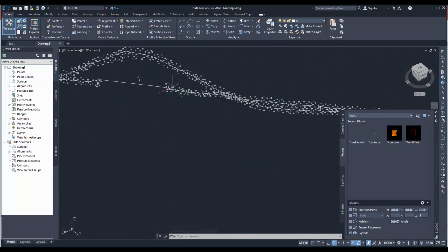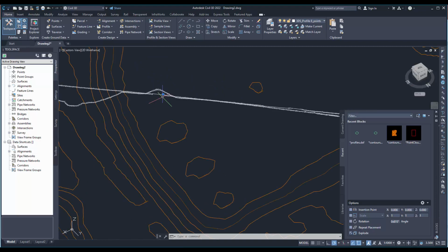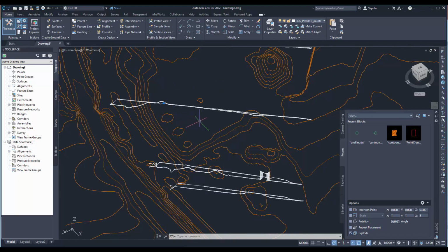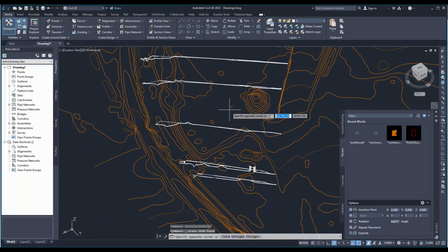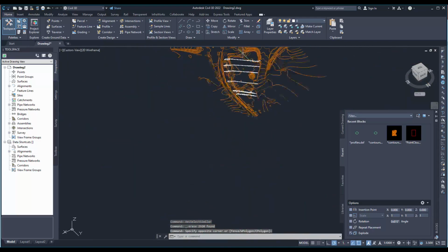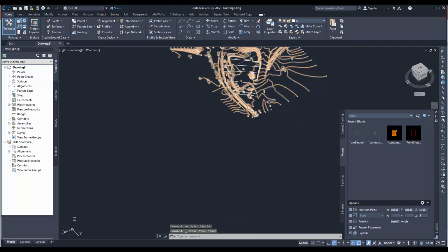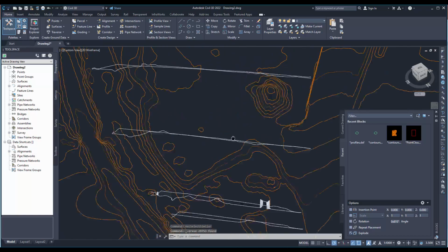One thing I actually recommend you to do is, here you see, with the profiles we also export the points which were used to define the profile. These aren't strictly necessary. We can use this one, select similar, to select all of them and then just press delete. We'll do that on all the cross sections right now, like that. Left select, select similar, delete. Now we should be left with the profiles only. Perfect.